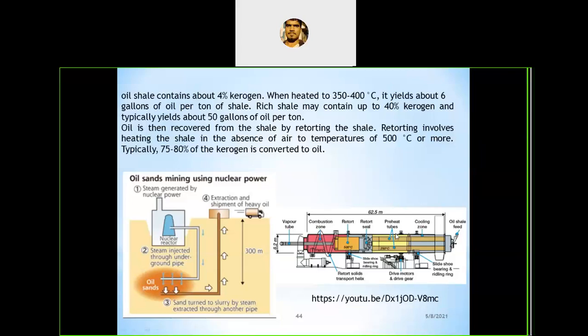It is a very low combustion energy. This energy is nearly equal to the combustion of wood, high grade wood. But when you compare with petroleum, diesel, or high grade coal combustion, the combustion heat range is nearly 40,000 or 50,000 kilojoules per kg. But here the range is 2000 to 17,000 kilojoules per kg. So the efficiency is very less when compared to coal or other petroleum products.